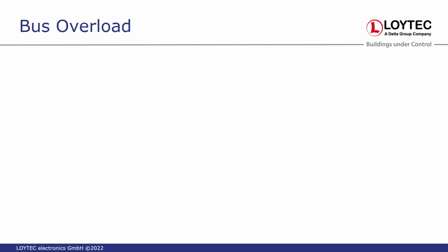Either you're running out of power, then you will get a DALI supply power failure, or when you scan the bus, you will find fewer devices on the channel because you cannot assign more than 64. So these are two different things, but in any case, you can use a maximum of 64, maybe less depending on the power supply and on the devices that you have.